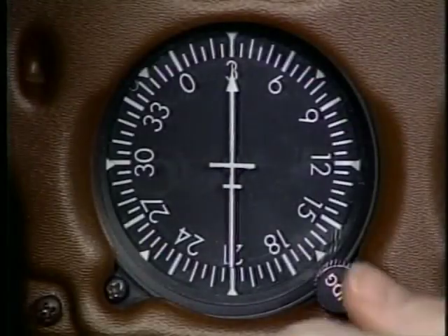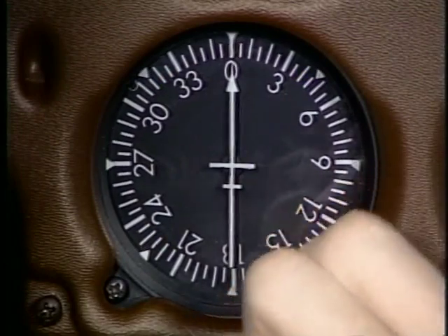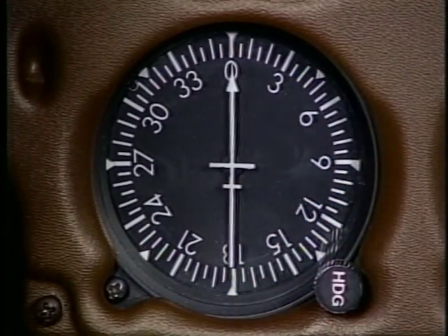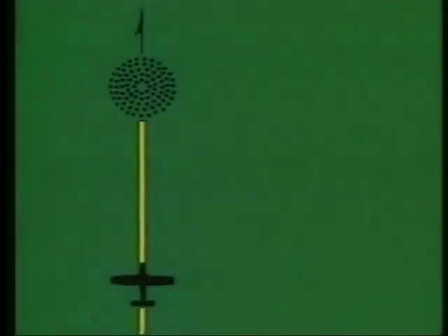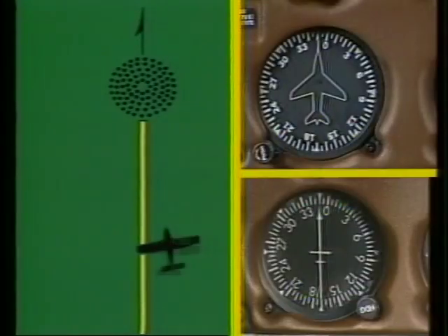Since the ADF does not automatically provide a wind correction angle as a VOR does, let's review the bracketing procedures. In this example, you've drifted right of the 360-degree bearing to the station. The ADF is sensing a crosswind by pointing to 350. To regain the course, you apply a 10-degree correction into the wind and reset the ADF to match your heading. If your heading and relative bearing remain constant,